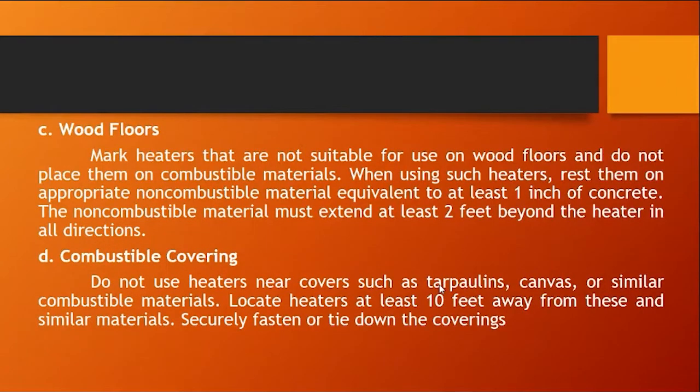For wood floors, mark heaters that are not suitable for use on wood floors and do not place them on combustible materials. When using such heaters, rest them on appropriate non-combustible material equivalent to at least 1 inch of concrete. The non-combustible material must extend at least 2 feet beyond the heater in all directions. Next is combustible covering. Do not use heaters near covers such as tarpaulins, canvas, or similar combustible materials. Locate heaters at least 10 feet away from these and similar materials. Secure, fasten, or tie down the coverings.